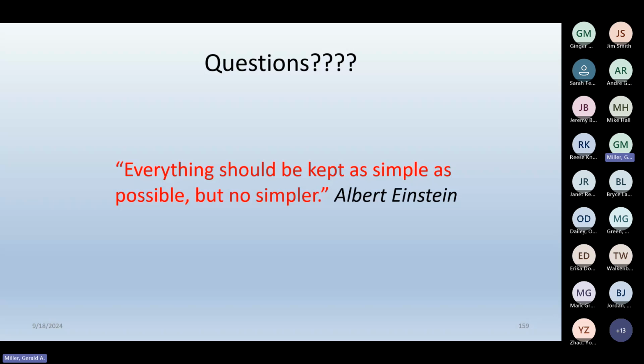If we want to start incorporating this into our analysis, we can do something. We don't have to do nothing. And whatever you do is going to be conservative over just going with what you have on that particular test date, unless you happen to be in a very saturated, wet condition when you test, then you don't have to worry too much. That makes sense? So I think 20%, that's better than nothing if you expect there to be an increase in moisture content.